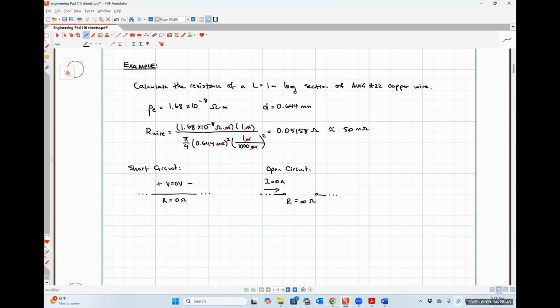So what's happening there is effectively the potential difference that's seen between the blades inside of the outlet and the blade of the plug, when they're separated, the gap gets so small that we're able to break down that dielectric medium and cause current to flow across that open circuit.